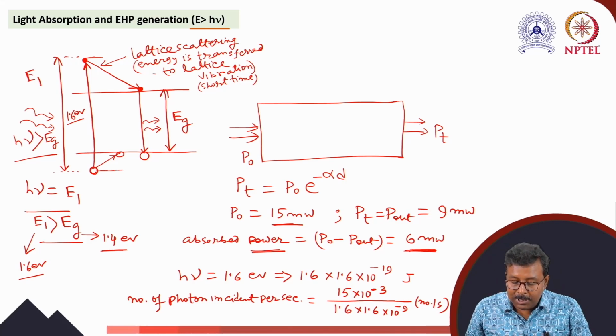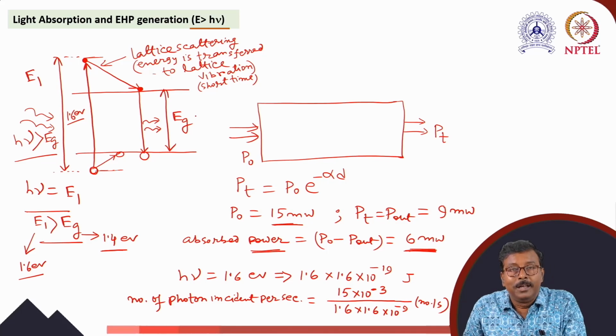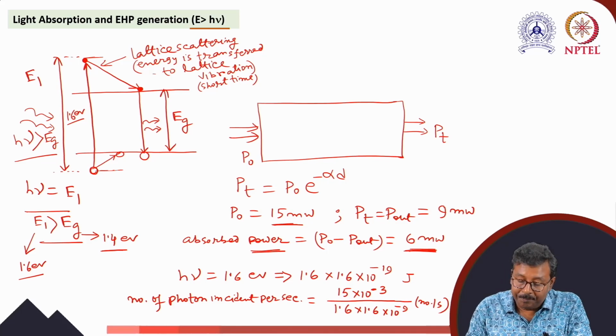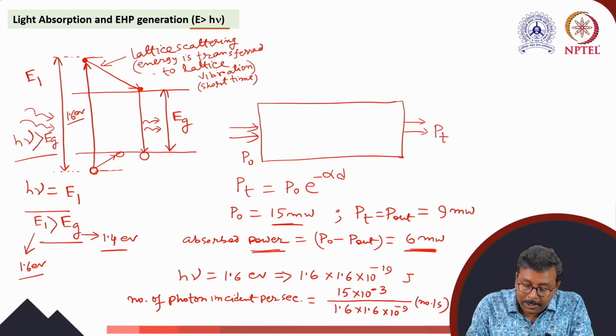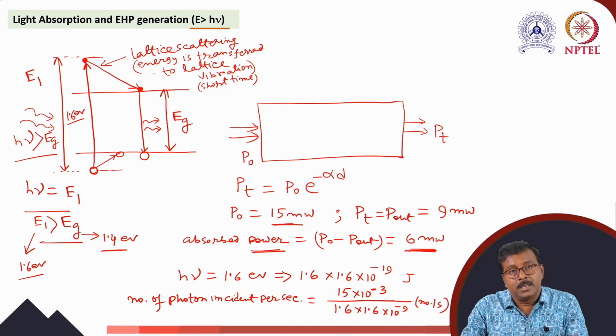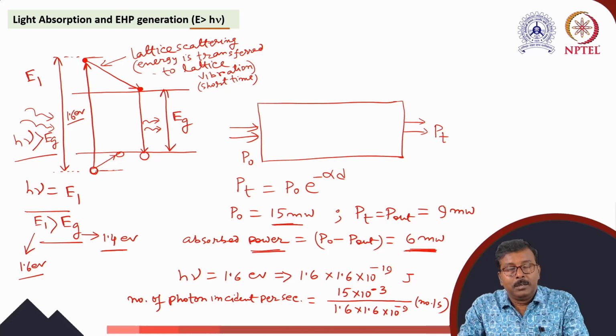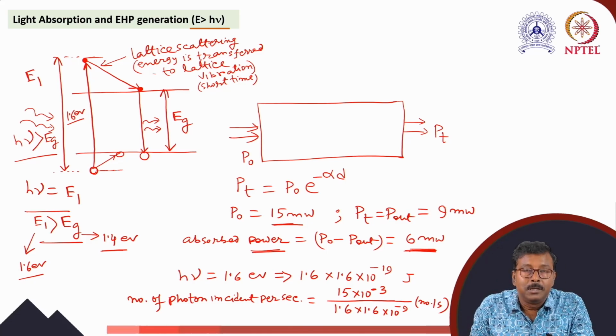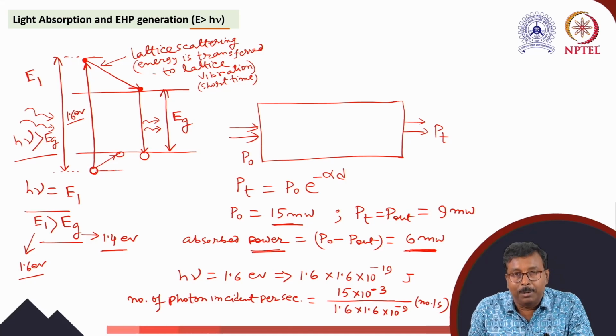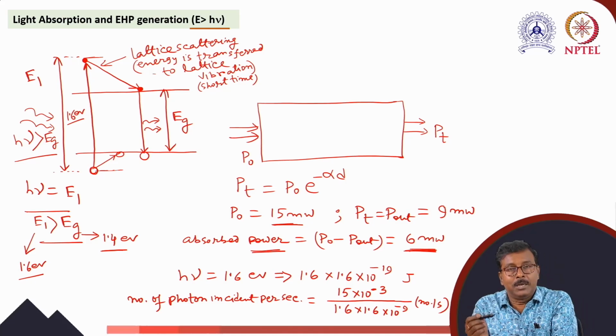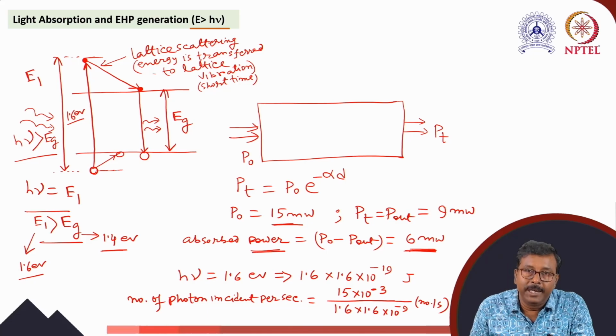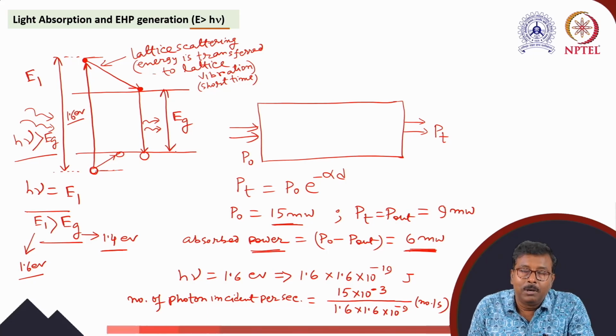incident. So what is the number of photons coming out? If we consider quantum efficiency, perfect quantum efficiency means each recombination of an electron hole pair gives radiation or photon. So if there are 10 recombinations, 10 photons will be coming out. Generally, out of 10 recombinations, 10 photons are not coming out. Some recombinations radiate some heat energy also. So in that case it will not be 100%.